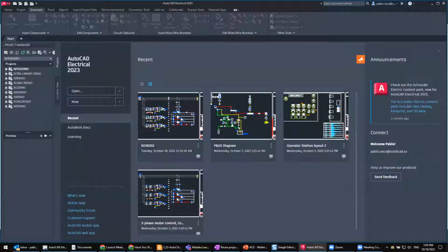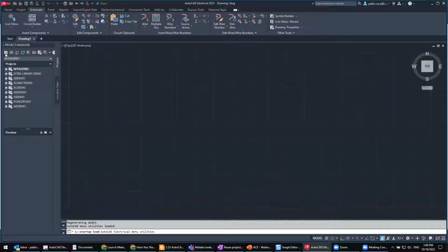Okay, so let me switch to my AutoCAD Electrical here, and let's get started. All right, so let's start with creating a project-specific database. All this is going to lead to the point where we start talking about the master project. To create a master project, we first need to create a new project, of course. If anybody has used AutoCAD in the past, you already know how to do this. So all I'm going to do is quickly create a new project in here.